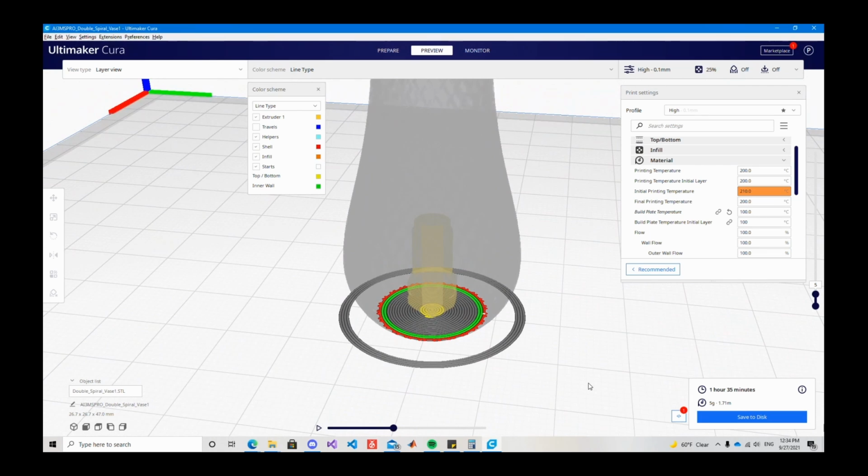And so build plate adhesion is the biggest thing that a lot of people run into. And so people put different types of adhesives on the build plate, whether it be glue or hairspray. My printer doesn't need it. It has a special coating on top of it. So as time goes on, you would need to replace the build plate because the coating leaves.